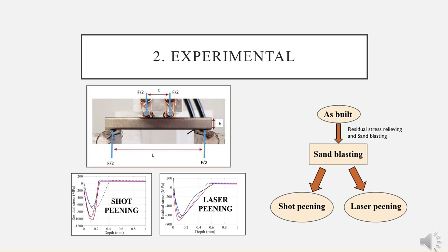We are interested in studying the evolution of cracks emanating from internal defects, which is usually the case in both shot-peened and laser-peened specimens, due to the compressive residual stresses left close to the surface, promoting crack initiation inside the part. The residual stresses left in the material have been measured and can be observed in this slide. Fatigue tests were carried out in a 4-point bending setup, as schematically shown in the figure, with rollers separated by 15 and 70 mm, respectively.